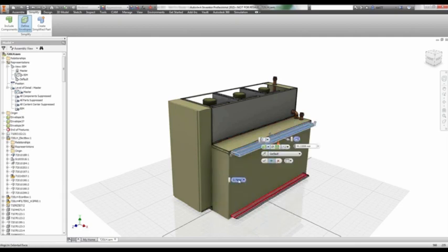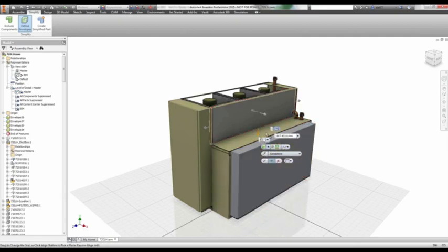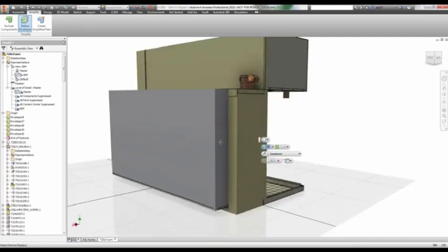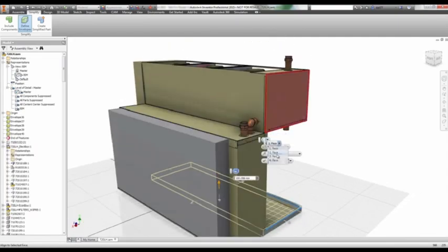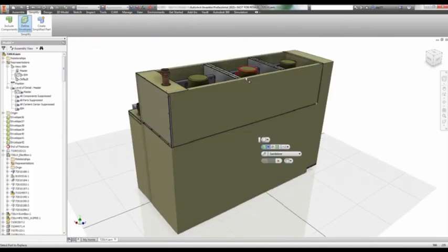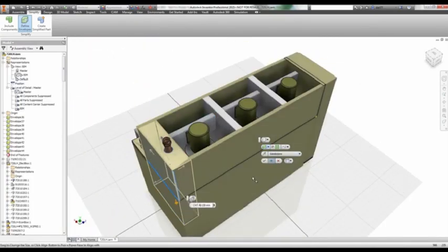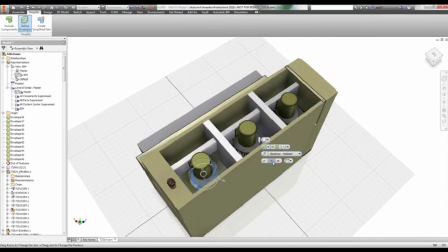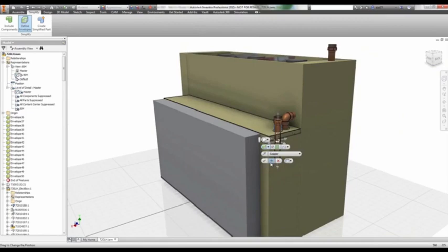So what I've got here is my full manufacturing model at the moment, okay? And what I'm simply going through now, you can see here that it's made up of different components and such like, but I'm now going through and using some of the simplification tools here to basically give me basic rectangles for the geometry that was included.